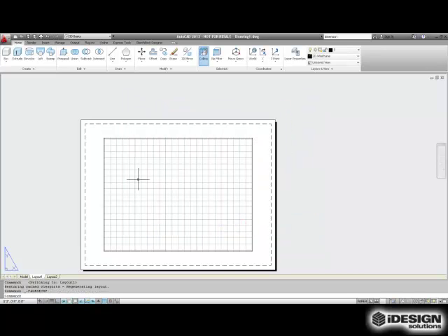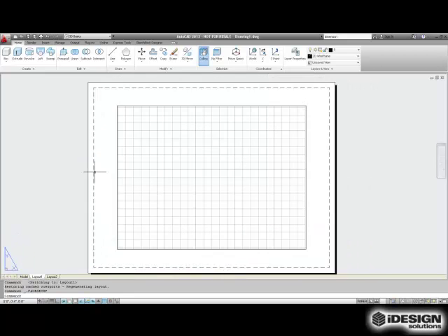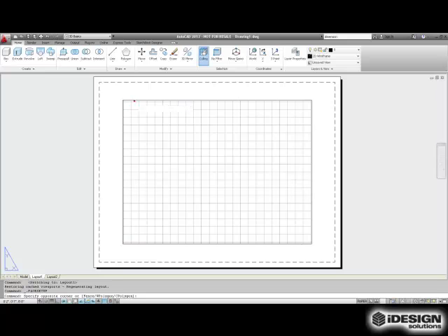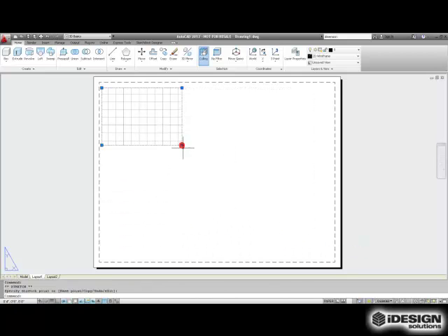So we'll exit out of here and take a look at the model space, or sorry, the layout space. Here is an illustration of how your sheet will look. You can take up more real estate of the page's current setup by changing the viewport, or you can create multiple viewports and access different aspects of your drawing set in one sheet.